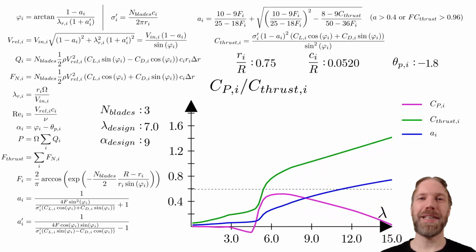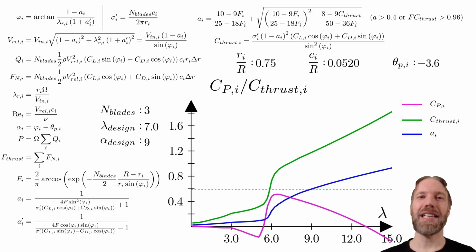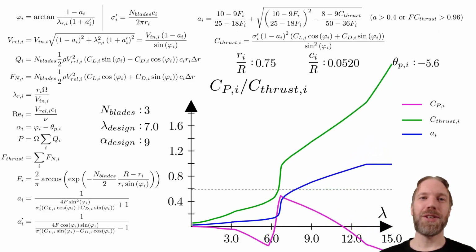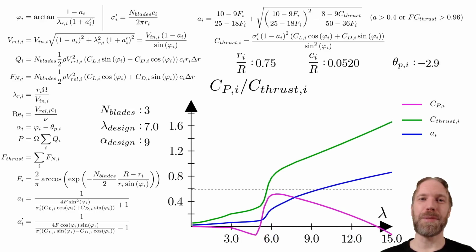We will now try pitch to stall and decrease the angle of attack. Note how the stall point moves to higher tip speed ratios. We can also observe that the thrust force at high tip speed ratios gets very large. I want to remark here that when we use power control, we will be at high wind speed, hence the tip speed ratio will be lower than normal. You should therefore not put too much focus into what happens at high tip speed ratio in this case. Let's return and end the demonstration.